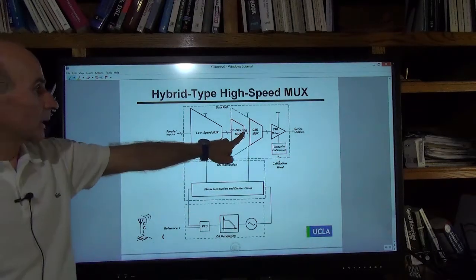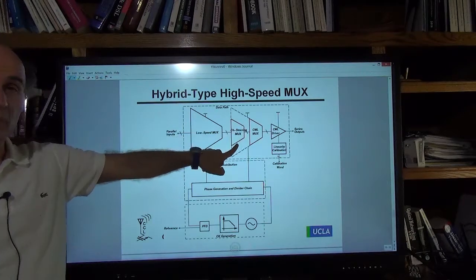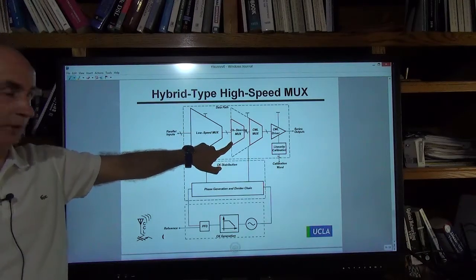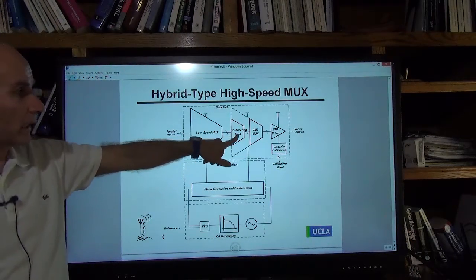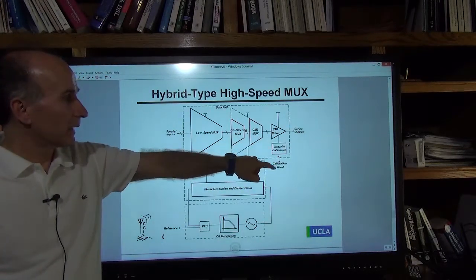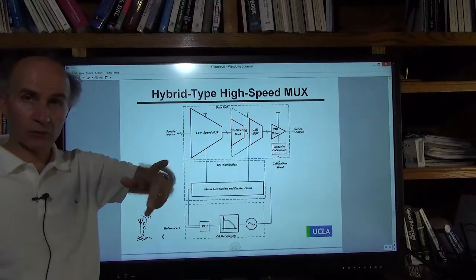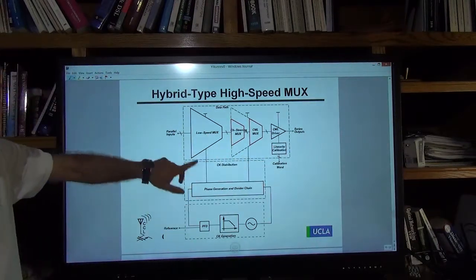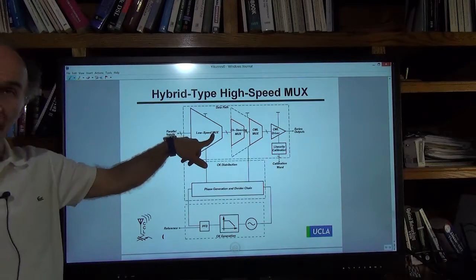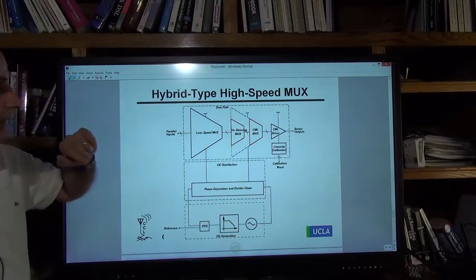Okay, so a few words about these things. First of all, the text should never run into the box. Okay, that's a big no-no. The text should be contained in the box. For example, like this is fine. Here, this R is almost touching or actually touching that edge. That shouldn't happen. Here, the text has become italic. It shouldn't be italic. This is just regular box labeling, so they shouldn't be italic.